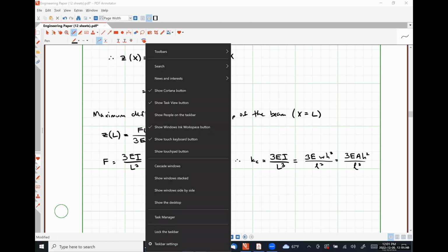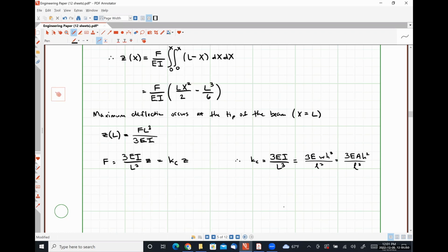All right, so I just wanted to compare those two spring constants. Obviously, we can see they're going to be vastly different mathematical quantities, but we should expect to see that our cantilever beam springs are significantly softer than an extension rod spring for literally the exact same beam shape, material, etc.